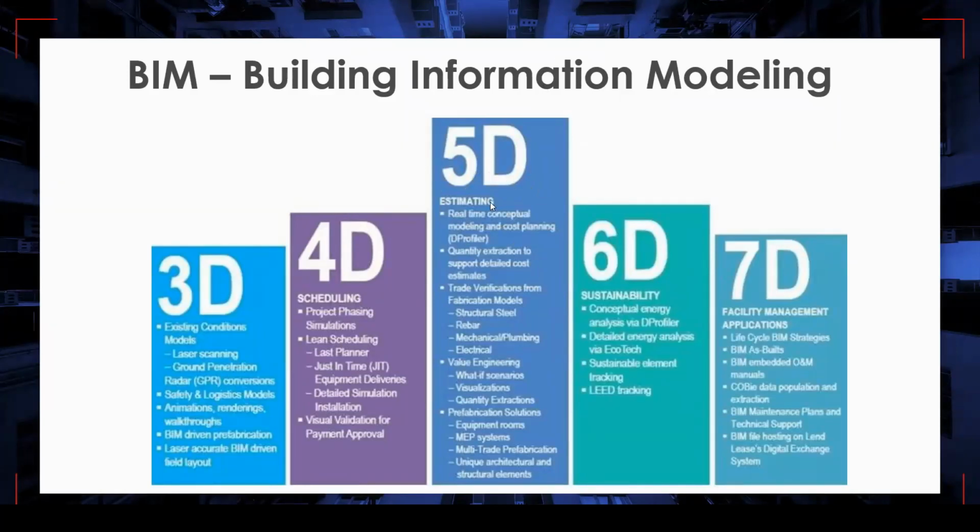Once you add the cost information to your system, you have the 5D BIM model. You can have the cost estimation from the tender stage or the proposal stage. You can use the BIM model for cost estimation, because actually the 3D BIM model is an information model. You have the geometry, quantities, and all the material coefficients. You can have every piece of information in your system, so you can directly take out the unit cost and estimate the project cost. Also, with the cost-loaded schedule, it allows us to control our cost with BIM usage as well.